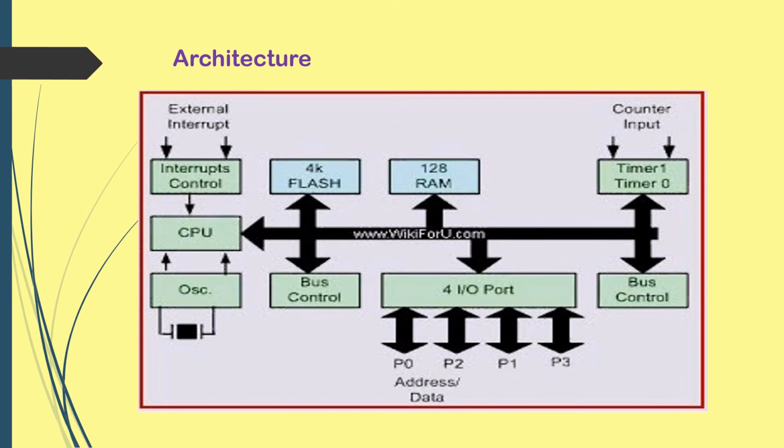As far as RAM is concerned, the 8051 is composed of 128 bytes of internal RAM. This is volatile memory, since its contents can be erased and are lost once power is switched off. The 128 bytes of internal RAM are divided into 32 working registers, which in turn form 4 register banks. For memory organization we will talk in detail later.